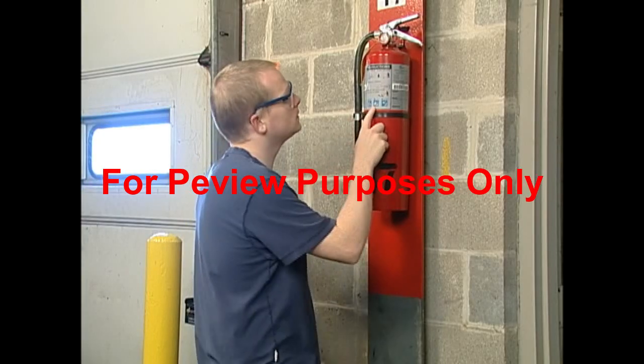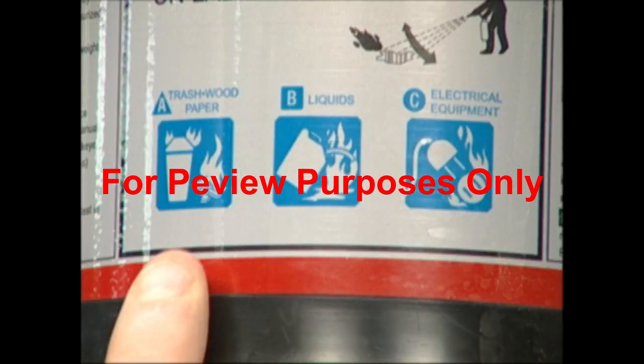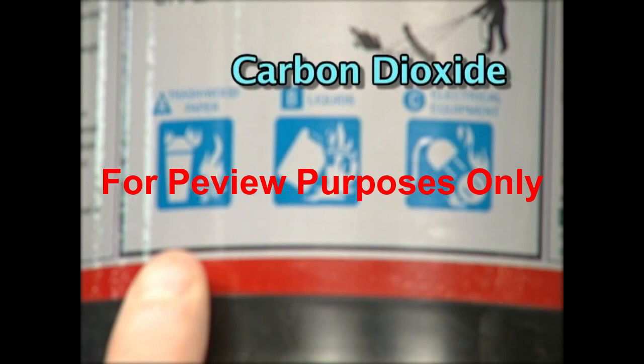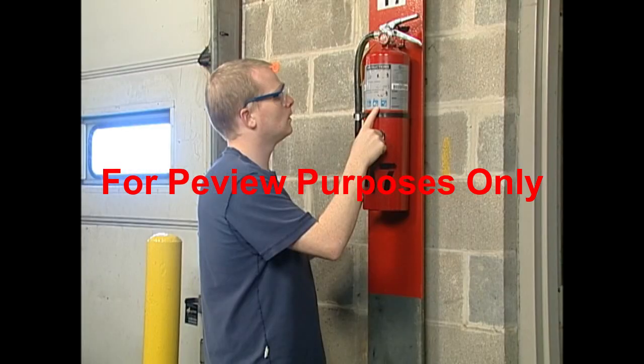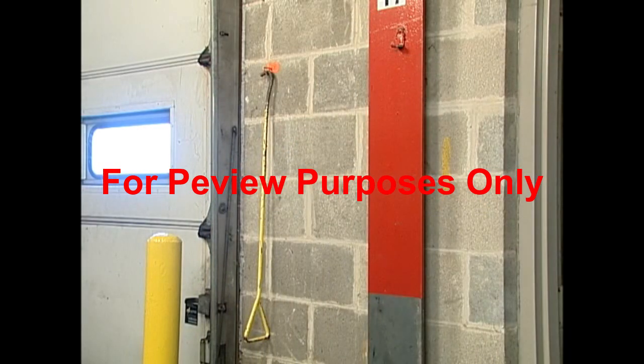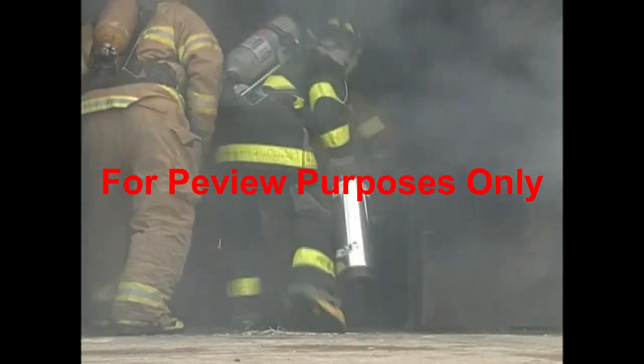When putting out a fire, it's important to use the correct extinguishing media. These can include water, water fog, foam, carbon dioxide, and dry chemicals. Using the wrong type could make a bad situation even worse. This part of the SDS tells you what media are appropriate for the material.